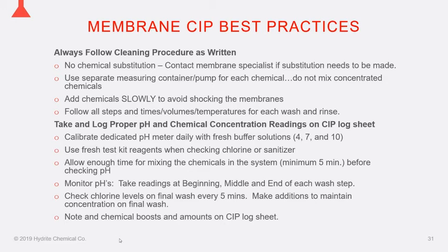So as my recommendation, if you're checking ROs and nano units, or any unit for that matter, the ideal place to take the sample would be out of the feed balance tank if they have a sample port in that. If they do not have a sample port, then take care, if you're going to get a sample from there, shut off any spray balls that may come on periodically while taking your sample to avoid being sprayed in the face and playing Russian roulette.